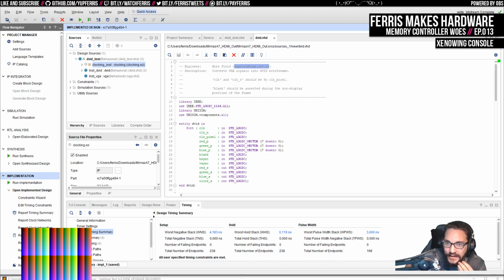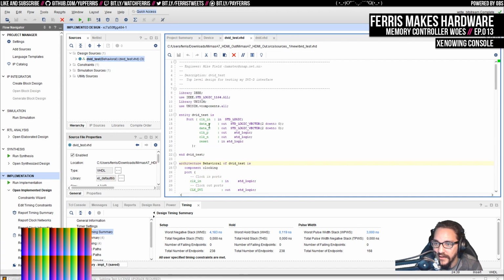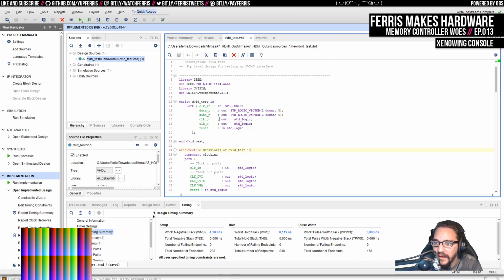We'll see. That's another interesting thing here: if we look at the top level ports here, the only things that are hooked up, I think, are the input clock, and these data outputs here, which I guess are the output of the TMDS stuff. These are 3 bits each, it looks like, so I guess this would be 3 differential pairs, if I'm reading this correctly. And these are differential signals. And then there's the output clock, which is also differential, and then the input reset. And that's kind of it.